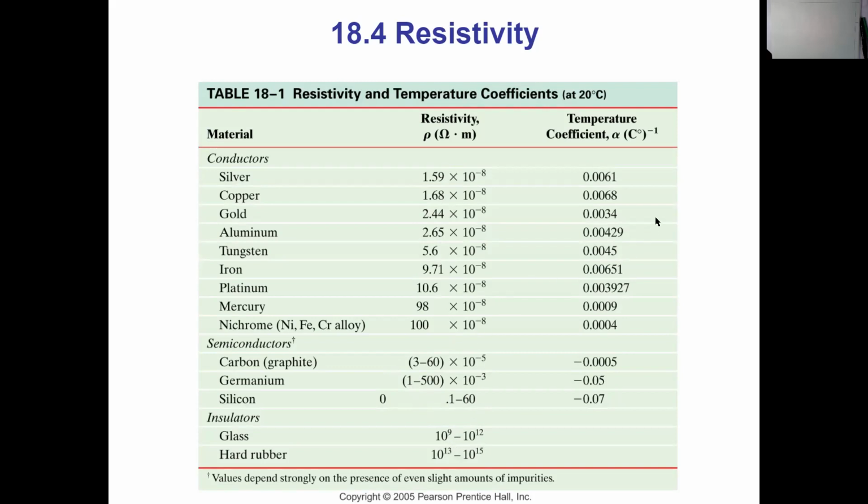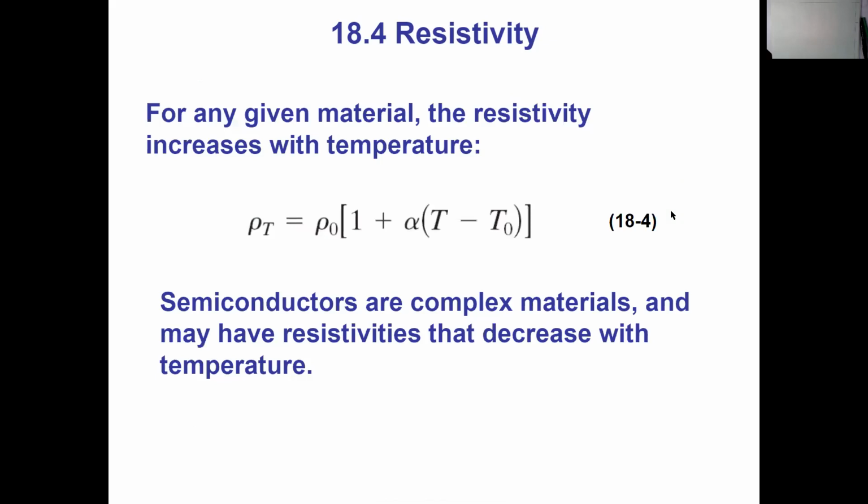We also see this temperature coefficient happening. And so this indicates that the resistivity is going to change a little bit depending on temperature. And we'll have a video that talks about some problem solving that goes along with this. So we start off with some base temperature, like room temperature, 20 degrees C. Then any temperature higher than that, like imagine a glowing light bulb, that's going to be pretty hot inside. And the resistivity is going to increase.